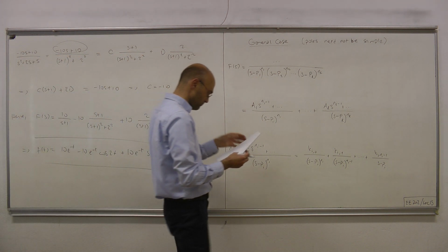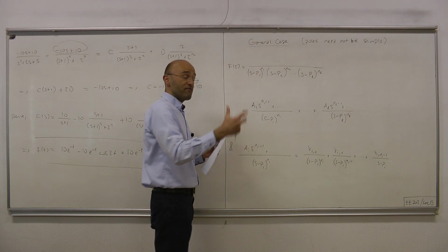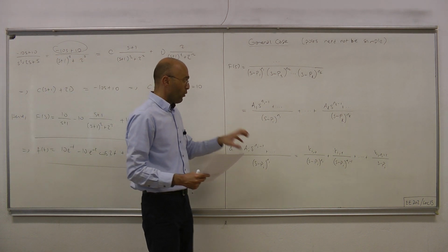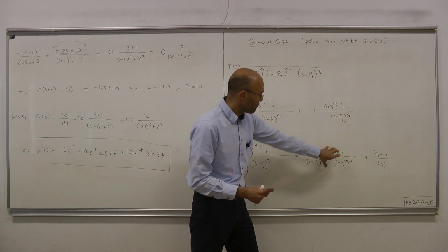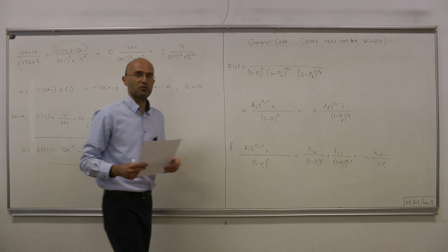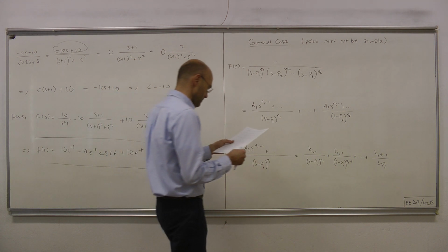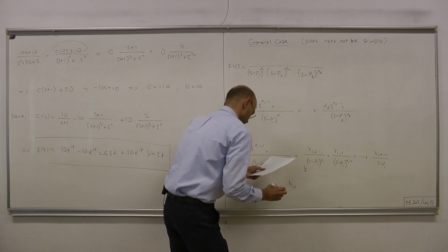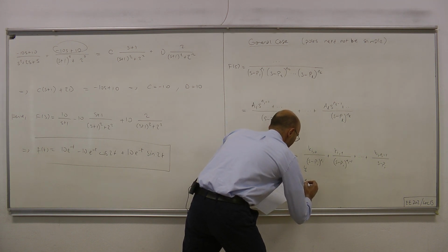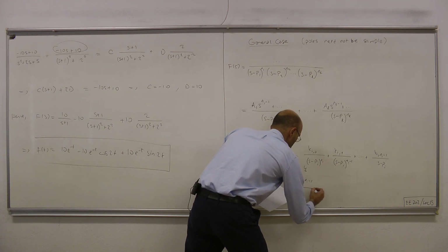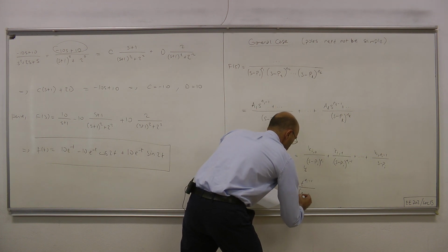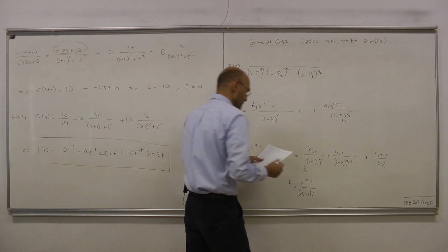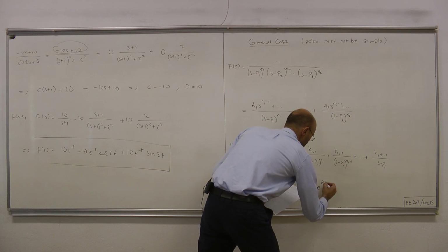Okay? And then, once we can decompose this into such Ni many terms, at that point, we recognize each of the terms as the Laplace transforms of some time domain signals. In particular, this guy produces Ki0 times t to the Ni minus 1 over (Ni minus 1) factorial, times e to the pi t.